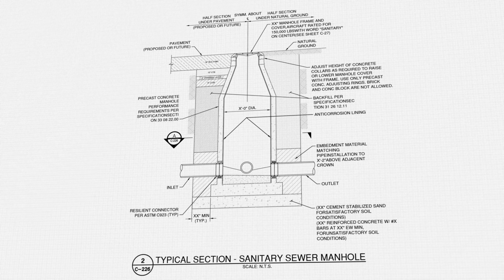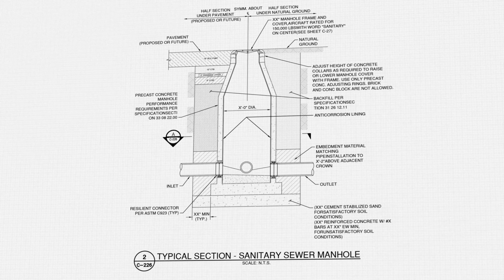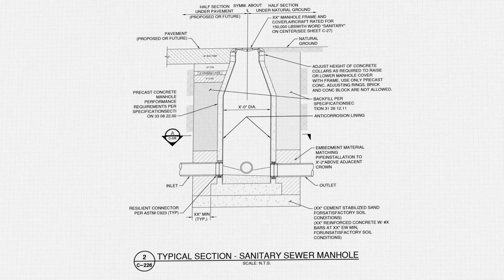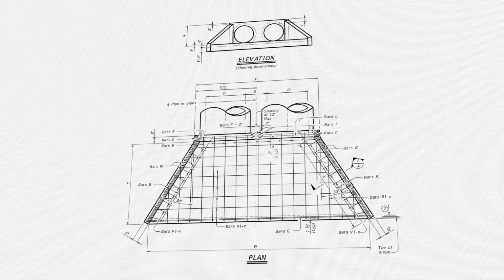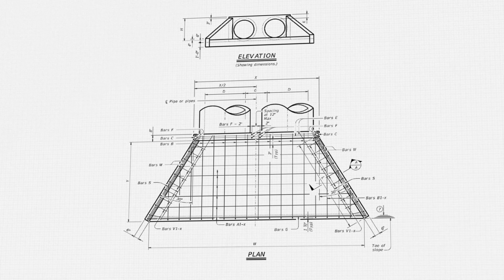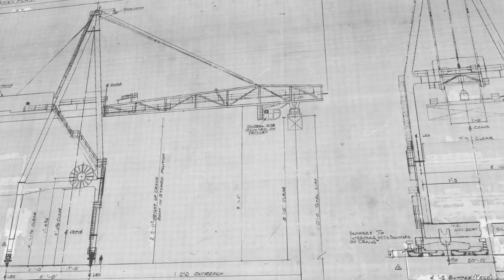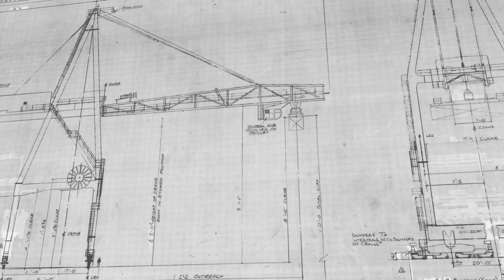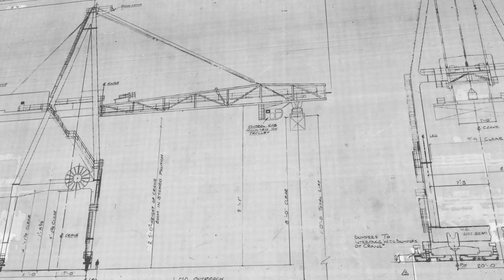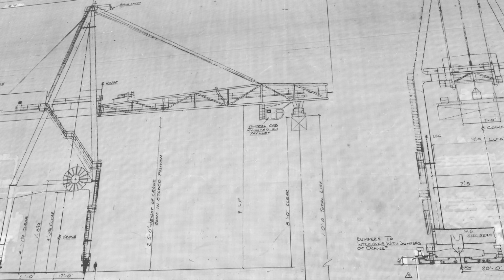Second, drawings. Drawings would outline the entire intent of construction, list all details and requirements. Contractors will be using drawings as blueprints for estimation and execution of construction. Reference drawings, if available, are also included at the back of the drawing set.